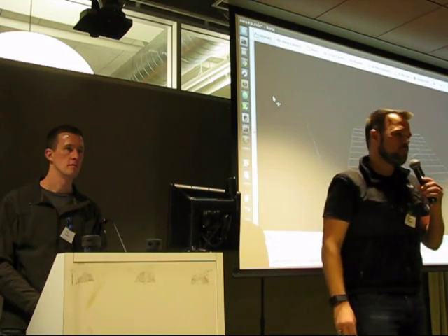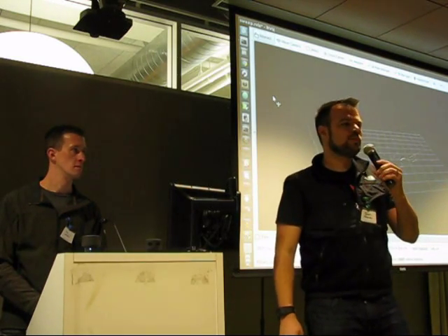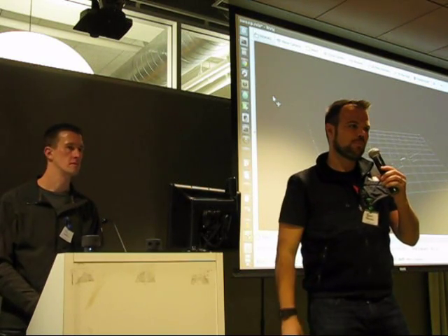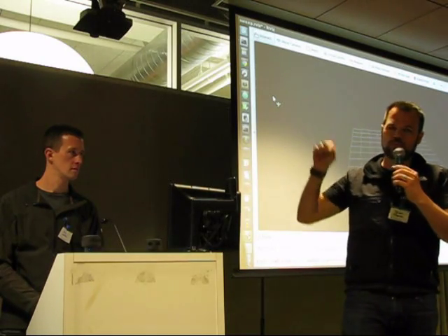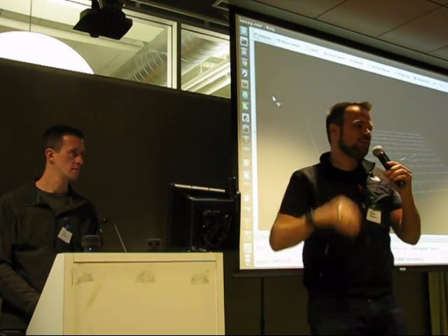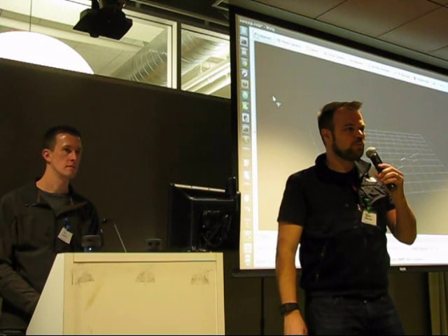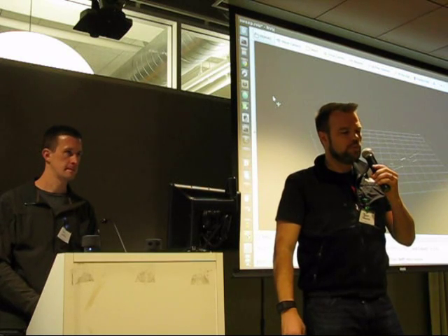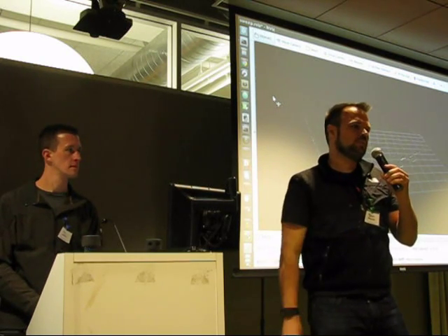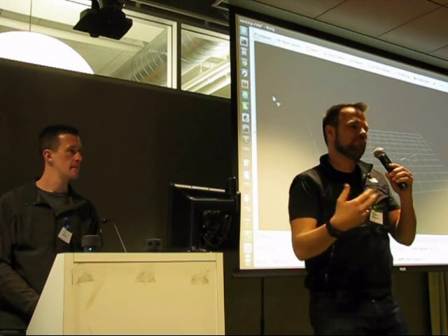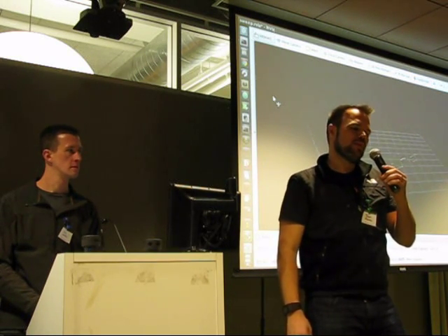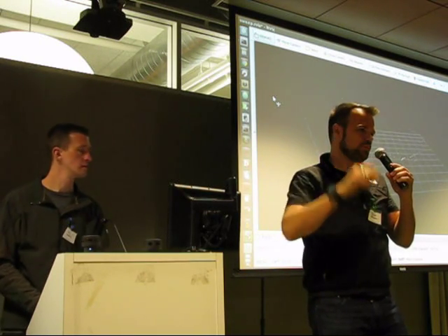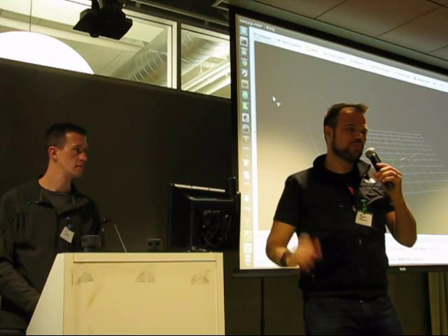How fast does the motor spin? Between 1 and 10 hertz is what we're allowing, and that'll be configurable in settings. We've actually got our own visualizer as well that gives you a menu of settings you can program it with quickly. 10 full cycles a second and 500 samples per second, exactly. That's the fastest you want to go, and that only gives you 50 samples per revolution, which is pretty coarse. It might be enough for quick object avoidance applications, but you wouldn't want to use that to map any obstacles.